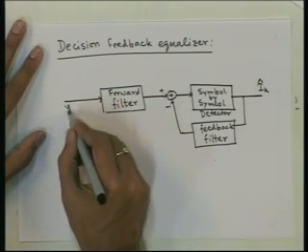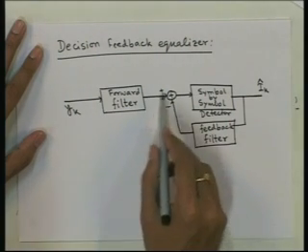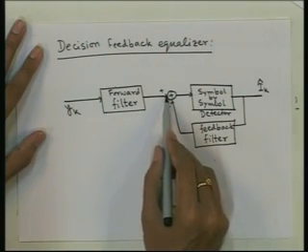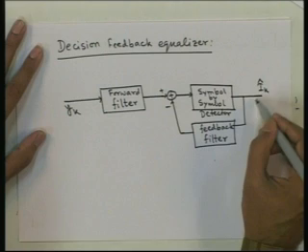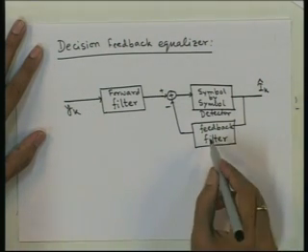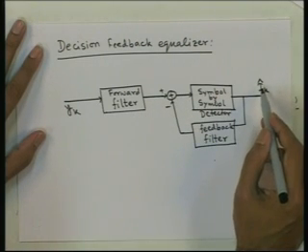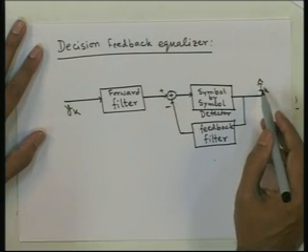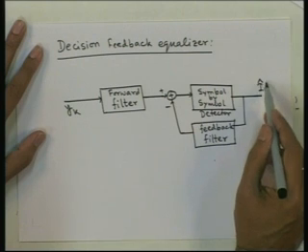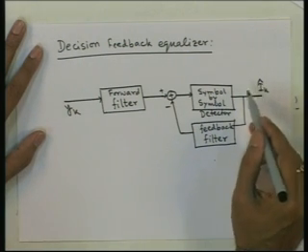So, we are receiving y k here, we are passing it through a forward filter, but at the end of it we are also removing the effect from the previously detected samples. So, we will design these two filters together, so that the error here is minimized. That is, we get I k hat which are almost same as I k.